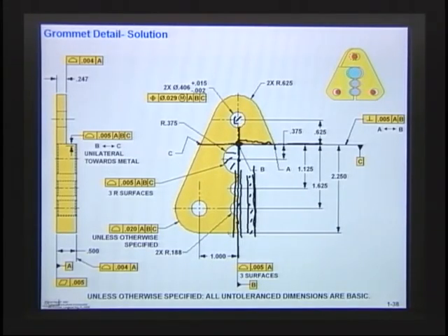Oh, for example, this outside, see, profile within 20. How many points are they going to check? Probably if it's a lot of tolerance, they're probably going to check less. If it's a tighter tolerance, they're going to check more. It depends on the process, how the part was made. Is this the first part you're checking, or the 100th part you're making? What's the tolerance? Who made the part? What do you know about the part?